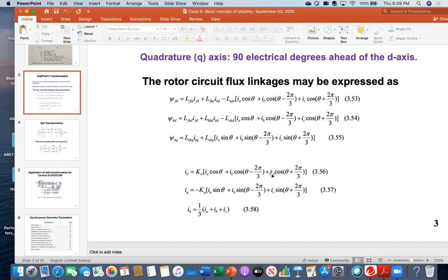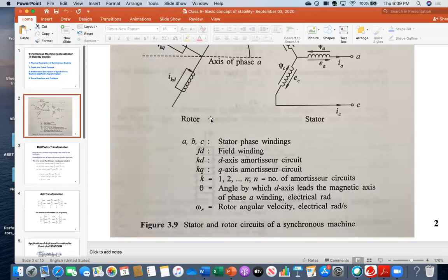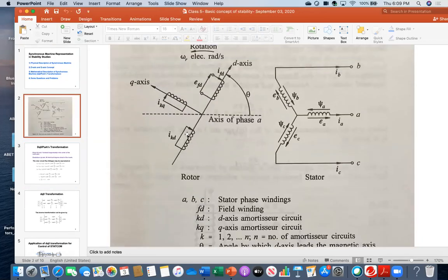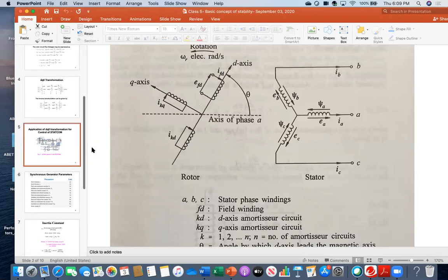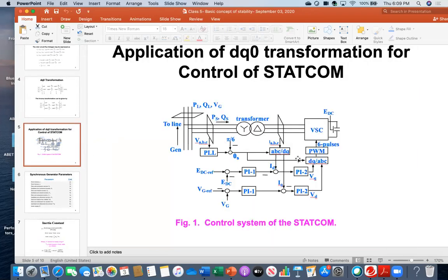Okay, there was a three-phase system here. Why not put three components here? But actually you see, here there was no zero sequence. Only there was D axis and Q axis. That's why frequently in control systems, it is converted into DQ components only. Just keep in mind. So anyway, then you convert it into DQ, and then what it is doing, everybody look.